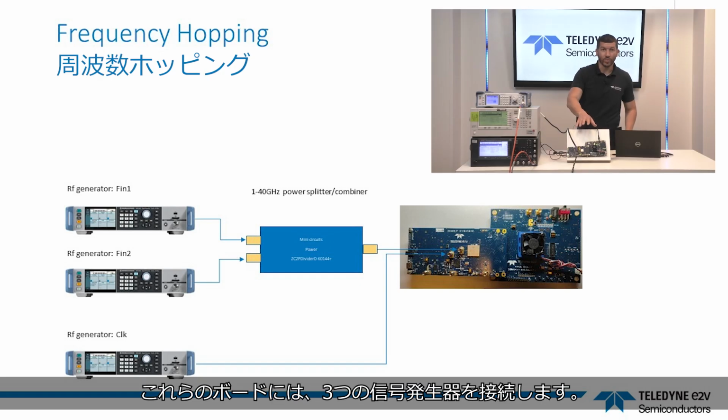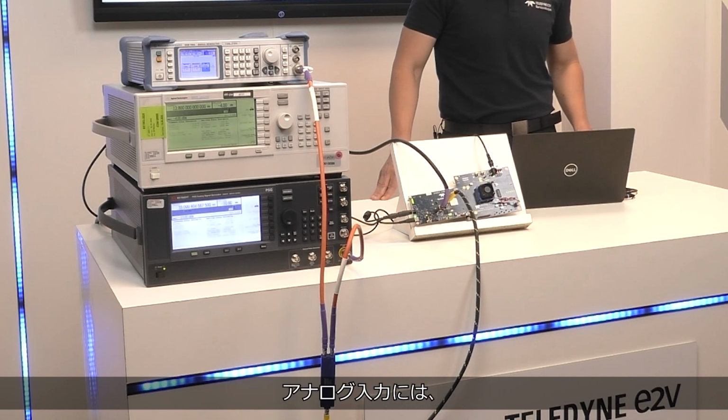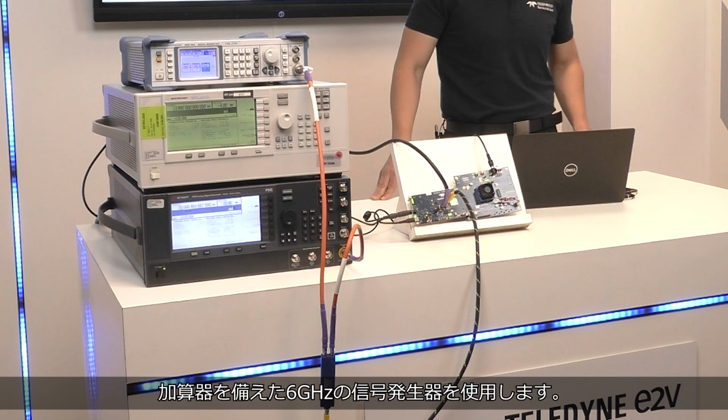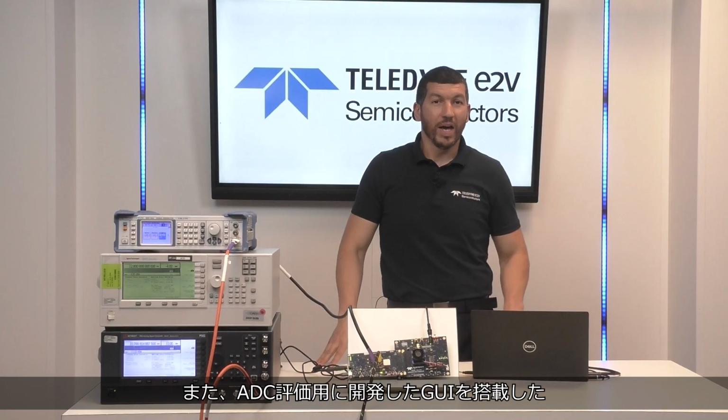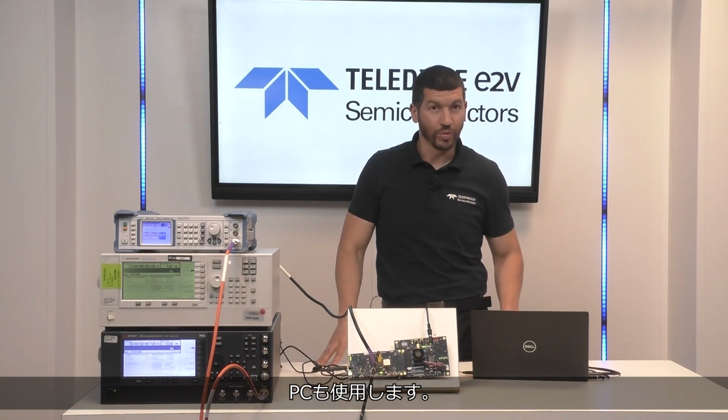Around these boards we have 3 signal generators. For clocking, we have a 20 GHz signal generator. For the analog input, a 40 GHz signal generator and a 6 GHz signal generator. And we have a PC with our GUI developed for ADC evaluation purpose.